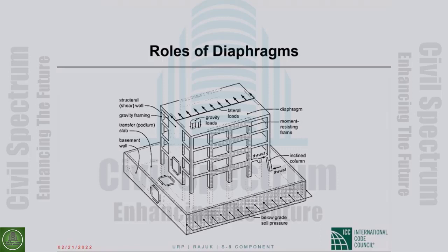In order to impose the live loads, we will have to resist the dead loads, the weight of the slab primarily, and we will also have to, okay, let me pause there. So the dead loads and the live loads are gravity loads that cause out of plane bending of the slab. And a slab has to be designed for that out of plane bending. We have to put reinforcement in to carry the out of plane bending and the accompanying shear.